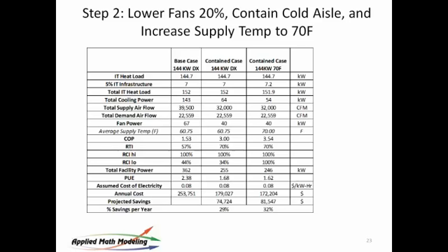These COP calculations will get more refined over time. We will continue to add more fidelity into the prediction model, but for now hand calculations are fair to give you an idea of where you are and where you might be. And here you can see savings of $81,000 a year by both raising supply temp, going to 80% airflow in this case, and containing.